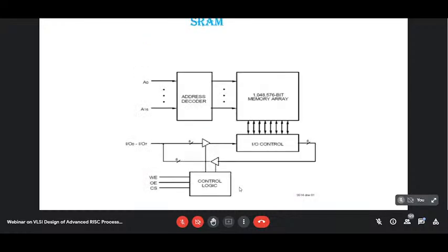And in fact, organizing this properly, like selecting the address. For simplicity, let's say there are 64 rows. 64 rows means you will require 6-bit address lines. 6-bit means 2 to the power 6 equals 64. One of the lines will be selected. So the address decoder will select one of the lines, and in that line, you can store the data through the bidirectional line.